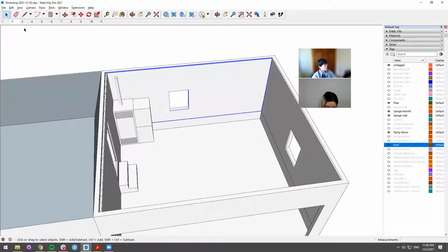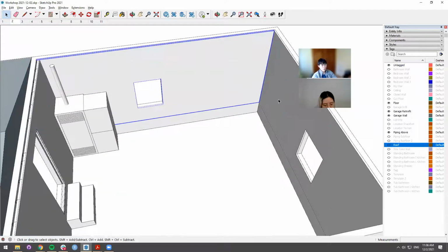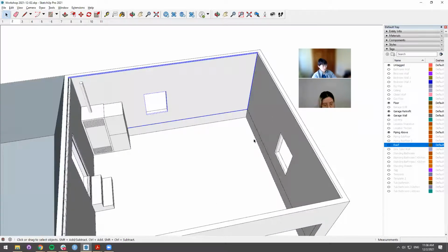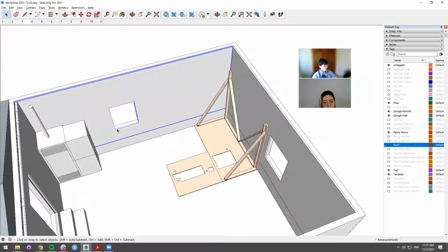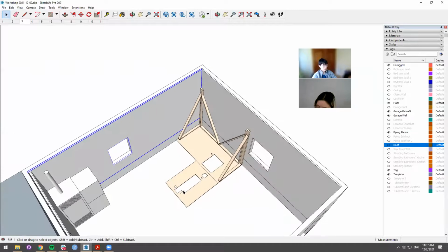All right. So then the next step here is one of our kind of novel, what we think are novel, but low-tech solutions, which is you need to be absolutely sure that what you build in the factory will fit in this corner and will fit in a level and flush way with exactly flush and level floor and ceiling and walls. And that may or may not be true. So what we propose doing at this stage is bringing in some kind of simple template that roughly sketches out what the dimensions of the overall module will be.